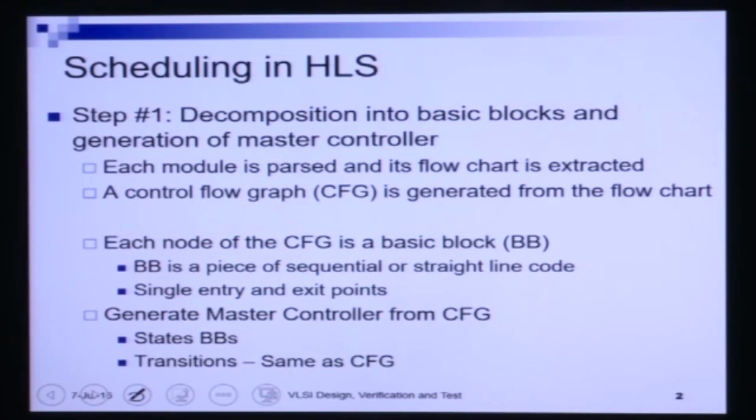Now, we also said that given this control flow graph with basic blocks and their dependencies, I can directly generate the master controller. So, what will the master controller control? The master controller will control when the operations in a basic block will be initiated, right. However, as we also said before, the complete master controller cannot be generated at this step, because the complete master controller will allow us to ascribe timing information to each operation in a hardware synthesized circuit. However, until we have ascribed explicit timing information to each operation within a basic block, we cannot ascribe the complete timing information of the module.